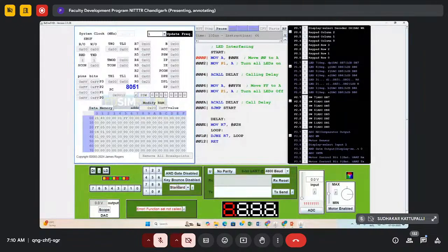In the same way, I want to tell you about the 7 segment display. In order to work on a 7 segment, suppose I want to display number 0, then whatever pin is connected to the center LED, I won't make that glow. This one is active low. Active low. Suppose I want to give 1.